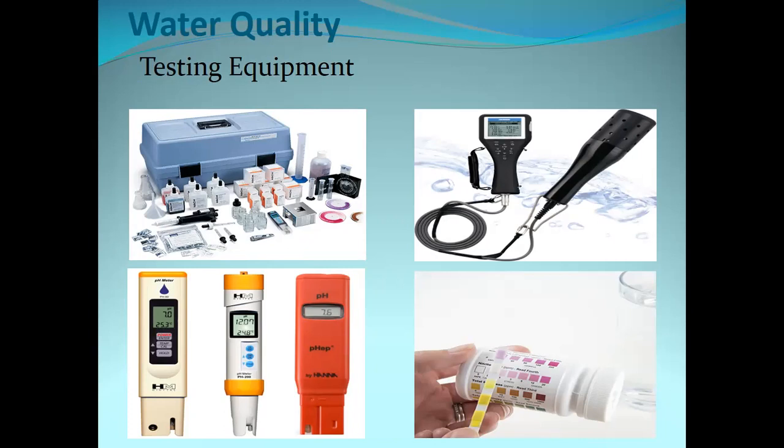The photo at the top right is a dissolved oxygen meter. You could actually take that, put the probe into the water, and it can tell you what the concentration of dissolved oxygen is, what the salinity is, etc. The meters at the bottom are relatively inexpensive, right? Those can measure things like pH. A meter like that costs around $185 to $200, somewhere around there, right?